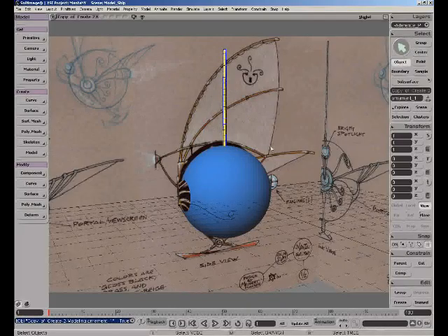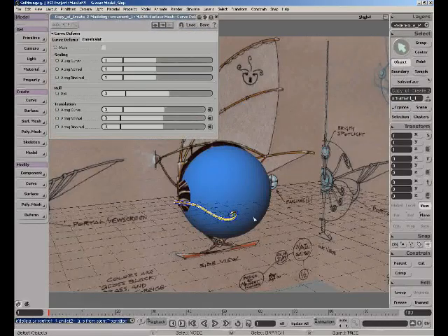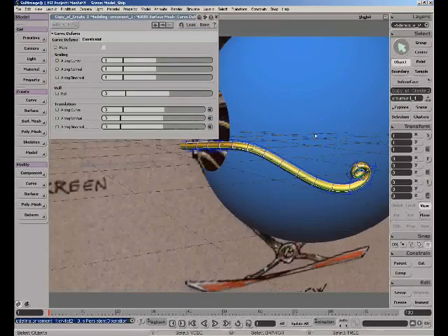So to do that, very simple. You're just going to go ahead, select the object, select the cylinder, say deform by curve, and then click on that curve. And you can see it automatically snaps to the curve. If I go ahead and frame up on that and take a look at our deform tool, you can see we've made a number of enhancements here over Softimage 3D. You now have the ability to control your scaling, your roll, and your translation all within one dialog box.